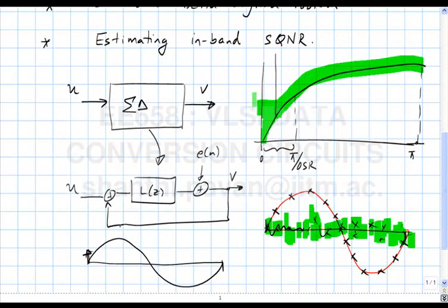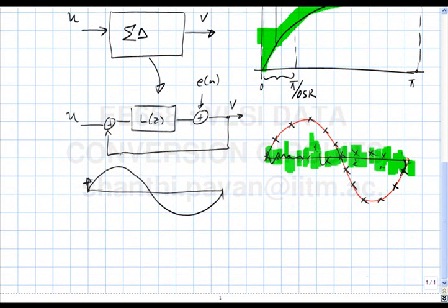So what do you do? You have to de-emphasize the edges. You want only the center. Just as we have discussed at great length in earlier classes, all you need to do is take the data sequence and apply a window. A popular window used for simulation is the Hann window.